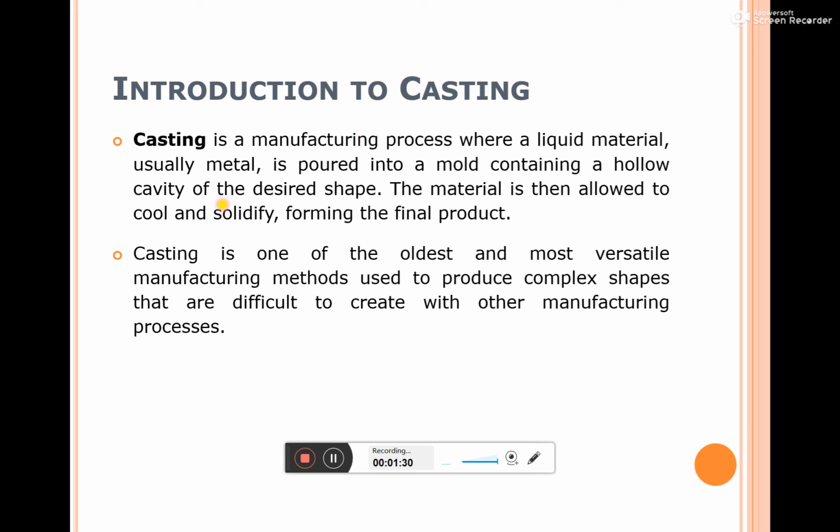melt the material. So, for example, I want to make a product or item using aluminum. Then I have to place this aluminum metal in a crucible. A crucible is a container made up of some refractory materials. So we put the billets or cut pieces of aluminum in the crucible, and after that, using different heating sources, like different types of furnaces, we can melt the